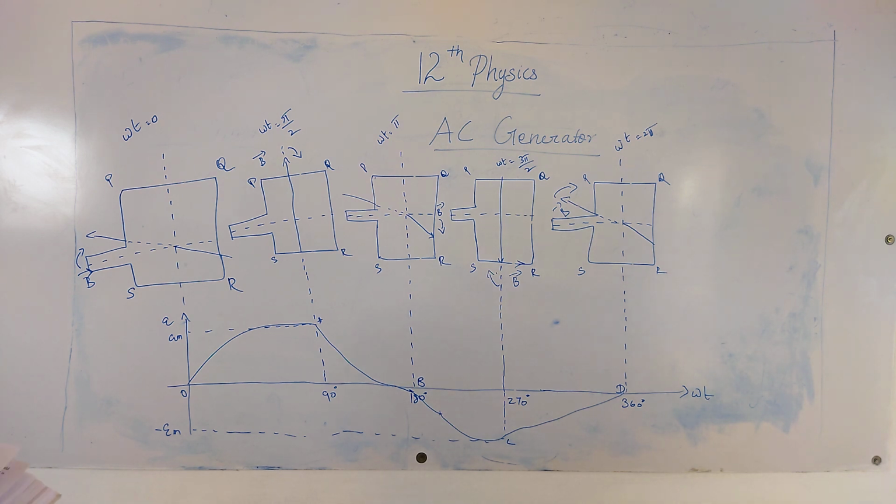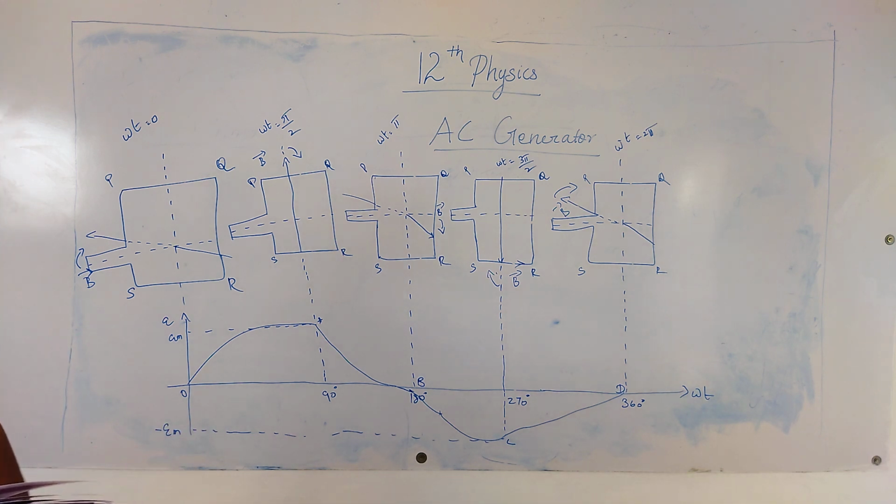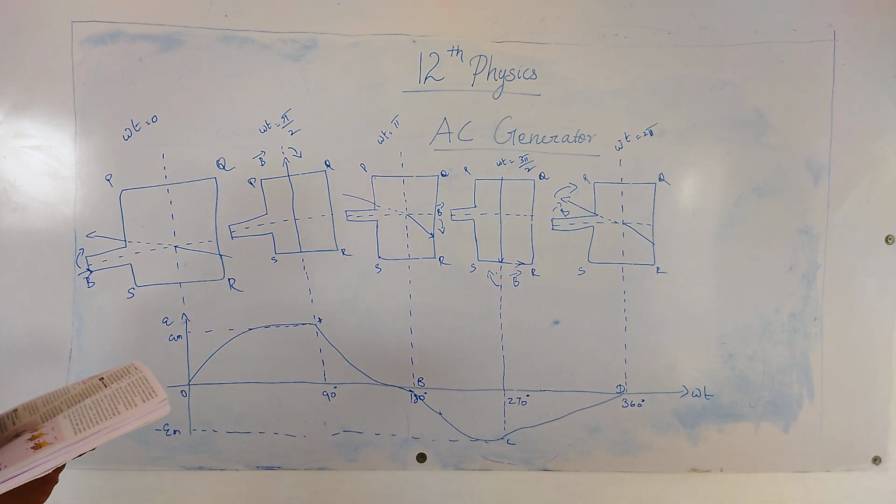And finally, we see the single phase AC generator. In a single phase AC generator, the armature conductors are connected in series so as to form a single circuit, which generates the single phase alternating EMF, and hence it is called the single phase alternator. Here the rectangular loop PQRS is mounted on the stator and the field winding is fixed inside the stator, and it can be rotated about an axis that is perpendicular to the plane of paper.